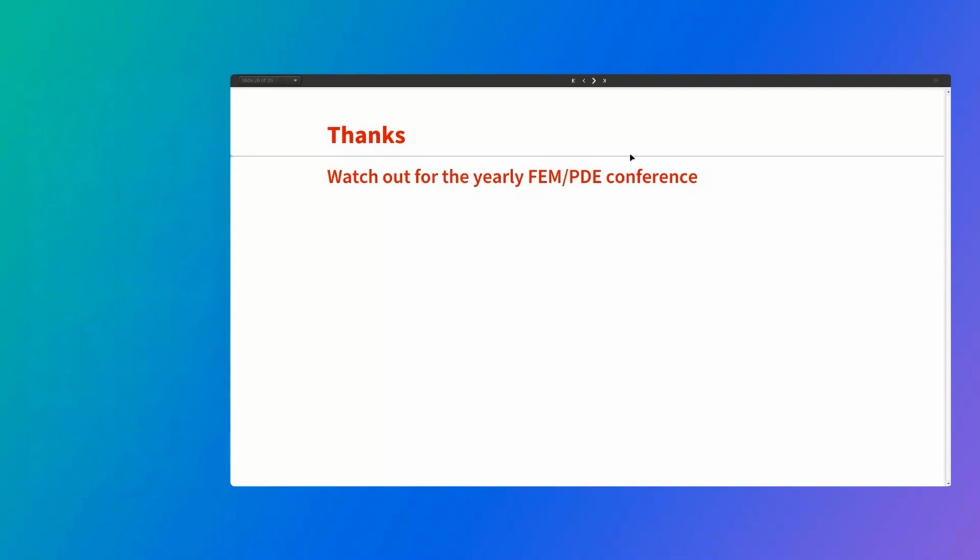One last recommendation I can give is Open Cascade. For 3D generation of complicated geometries, I typically say try to use the Open Cascade link, because that's quite powerful. You have standard conversions, but what's more interesting is probably the operations on these objects. You can do sweeps, Boolean operations, shape splitting, shape sewing, like internal boundary generation, fillets, chamfers, lofting, shelling. All these things can be done with the Open Cascade object. So if you have something more complicated, then I'd say Open Cascade is the way to go. I hope that answers the question a bit.